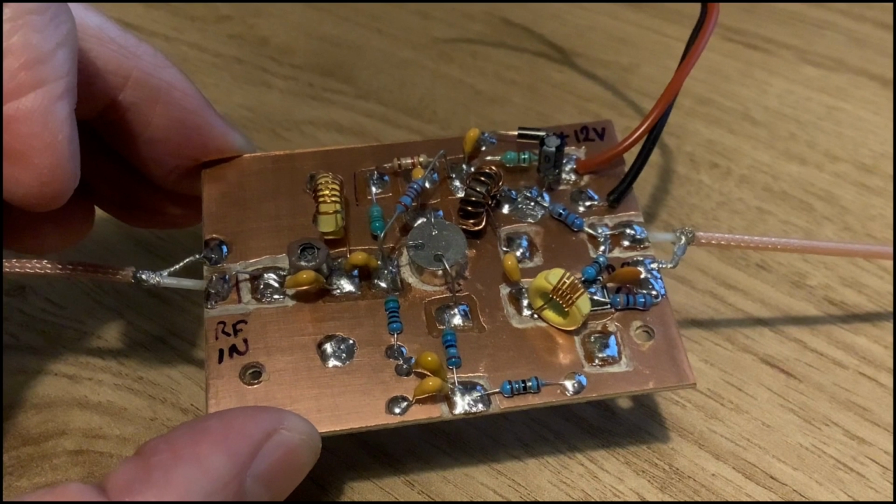So finally, putting all this stuff into practice. Here is the RF pre-driver that I featured a few videos ago now, and you can see here, this is the input. This is just the little DC blocking cap. So the actual input port of the amplifier is here. And this is my L matching network. And you'll see I've got series capacitance, and I've got parallel inductance, so you should know by now that that means this is a high pass filter.